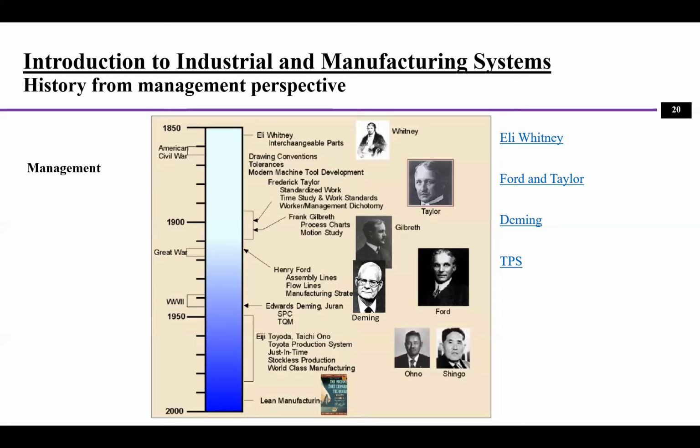And the Toyota production system, instead, created more of a toolkit of different methods to identify problems and then solve them. Also, for example, the Kanban system does the pull system, which means that you only make what you need, instead of the push system where you produce as much material as you have.